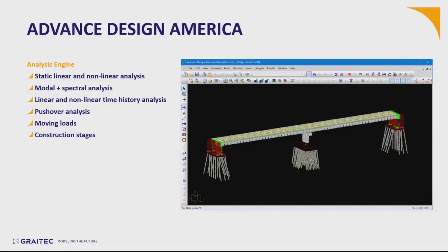Before jumping into the software, let me give you a quick introduction. ADA is an analysis and design tool based on finite elements. As the name suggests, it is made for North America and more specifically Canada. In terms of analysis, we can do linear and nonlinear static. It can run modal and spectral for seismic design. It can also do time history, pushover, moving loads, and it can also work with construction stages, which is very important for bridge design.